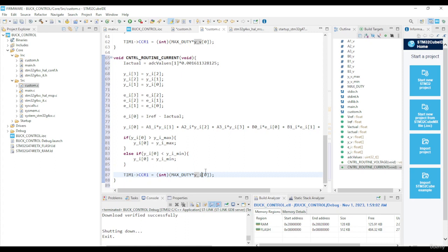All right. Let me just modify this. And secondly, what I also wanted to state, just a quick side step here, is that getting more accurate output voltage values for your set point actually has a lot to do with the resistors that are chosen as well. Because in the calculations, I'm assuming the values of the resistances are 910K and 100K. So basically what that means is, I'm using 5% SMD resistors.